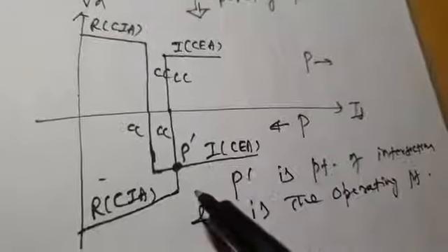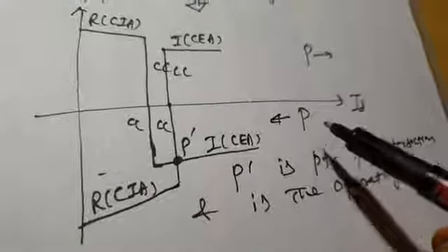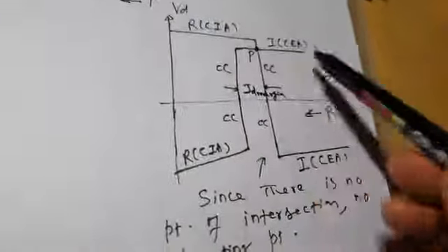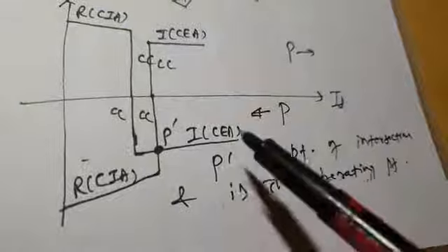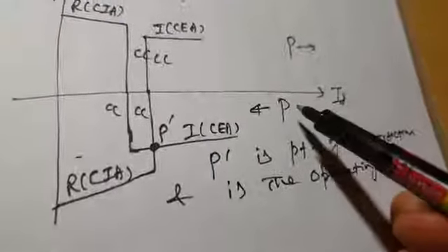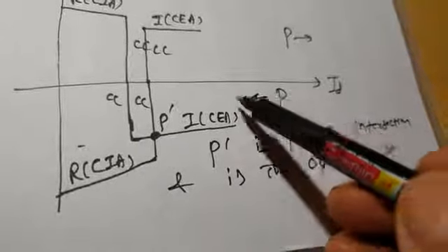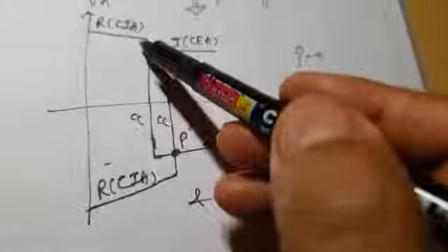Okay, so how was this possible? How was it possible to get the operating point for the reverse direction of power flow when we have swapped the currents of rectifier and inverter? In this direction of power flow, the rectifier current is higher than inverter current, and when your HVDC link operates in the fourth quadrant, I mean when power flow direction reverses, your inverter current is now higher than rectifier current.